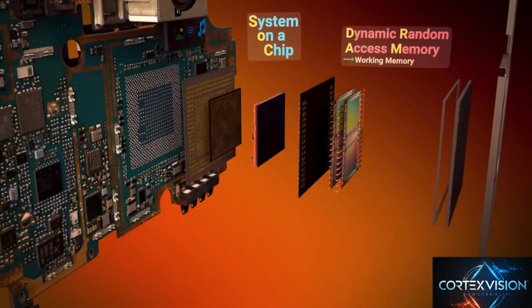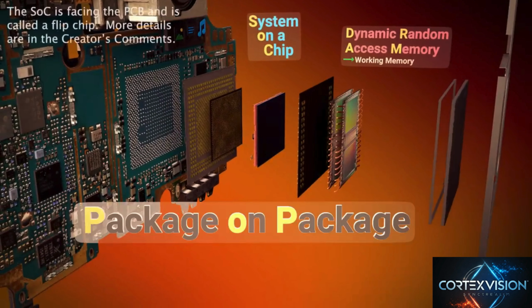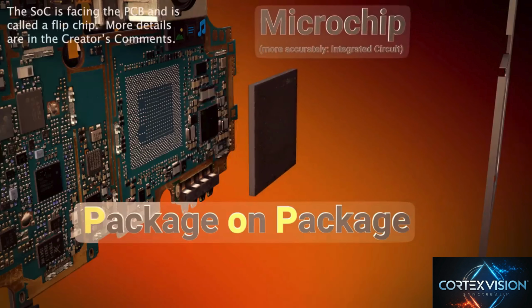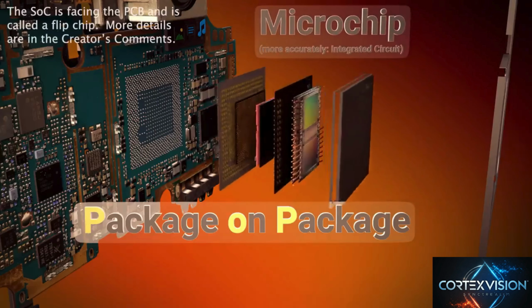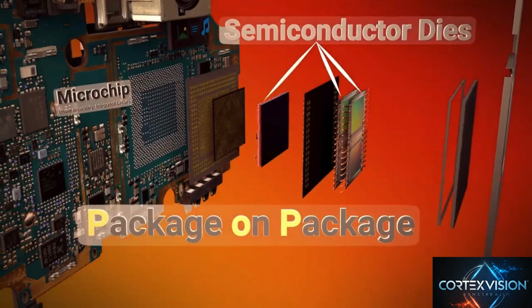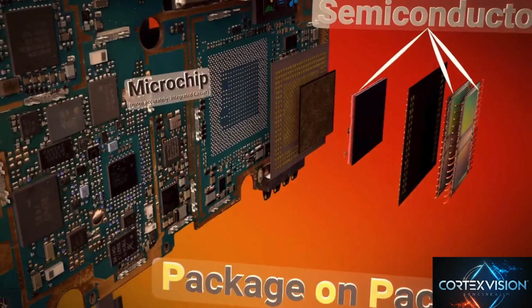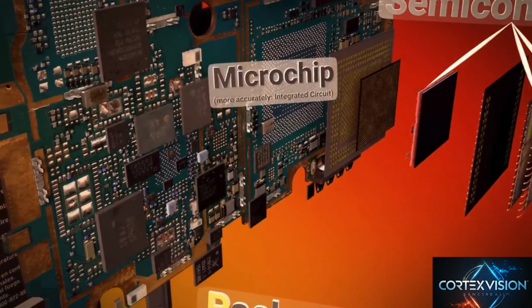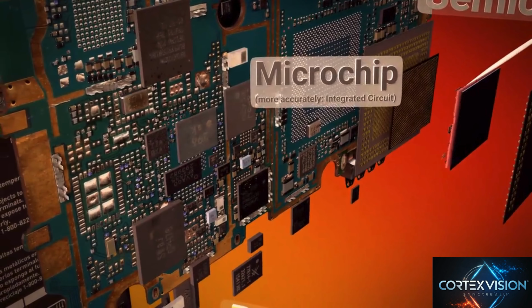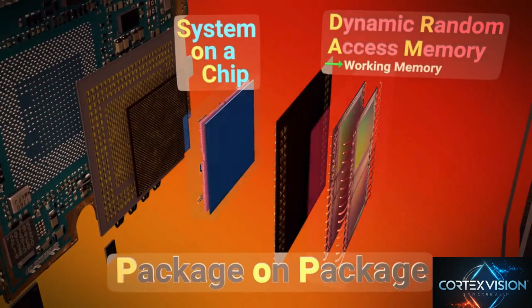This setup is called a package-on-package microchip, or POP. Technically, this is the microchip, and the separate layers of the DRAM and SoC are each called a die. However, the word chip has evolved to mean a variety of things. So, while all of these rectangular components are microchips or chips, both the DRAM and system on a chip are also called chips, even though they're just half of the overall package-on-package microchip.